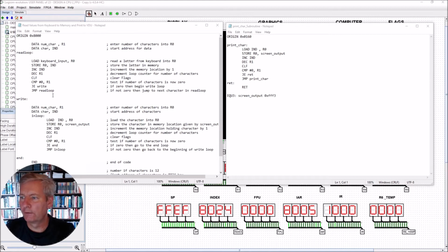On the left we have our original program which reads from the keyboard and prints to the screen. We've already worked through the reading from the keyboard. We're now going to work through the writing to the screen subroutine. So we're wanting to take this section here and generate the subroutine. Now I've generated the subroutine here. Now again, I have to pick a name for it, so I decided to call it print_char. So it means that whenever we use this subroutine, we're going to use the JSR space print_character. So it will go to the ROM and find this subroutine in the ROM.